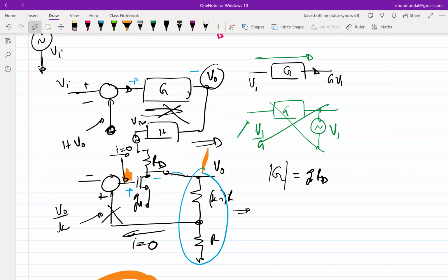The current source is supposed to put the current in, and let's assume that feedback and everything is working. So VGS will become appropriately developed, and all those things will happen. Now, when I break the loop and do this analysis, since I have a current source, I can simply remove the current source, right? So then whatever you are suggesting is going to happen. The loop gain will become gm times this KR, because RD will go out of the loop, right? So that is something we'll see in the next class.